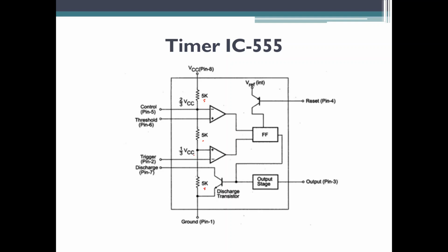So basically I told you, right, when I say it's a comparator, I need to give some reference voltages. The reference voltages are actually set by these resistive networks which are connected at the input side of the op-amp, and the reference voltage being set by these resistors is derived from VCC. So basically the supply voltage will be divided as per the requirement, and fed to the input pins of this particular comparator circuit which is built using the op-amps.